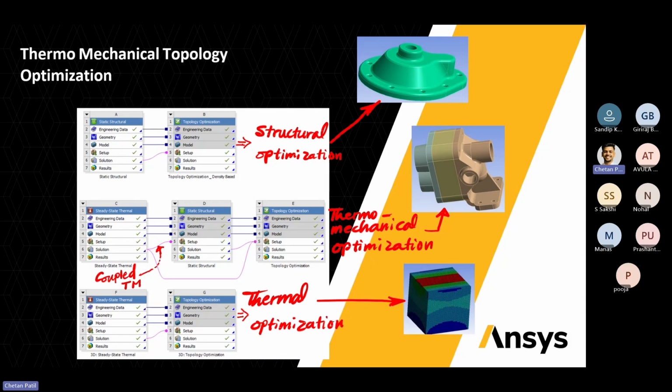As you can see in this slide, which showcases the combination, the static structural results are being used in the topology simulation. So this combination is called structural optimization, where we apply the structural conditions on the geometry under static conditions itself. But all the conditions that we consider in the simulation will be totally linear, because optimization doesn't allow non-linearity in the simulations.